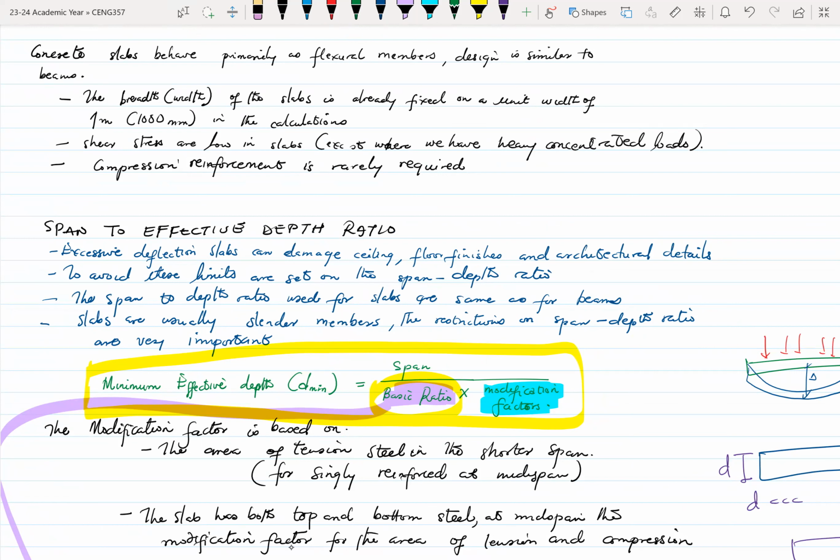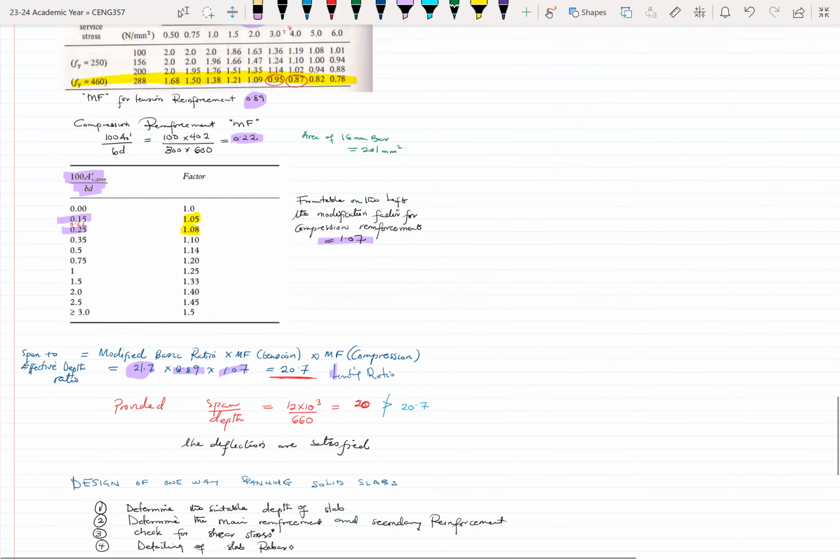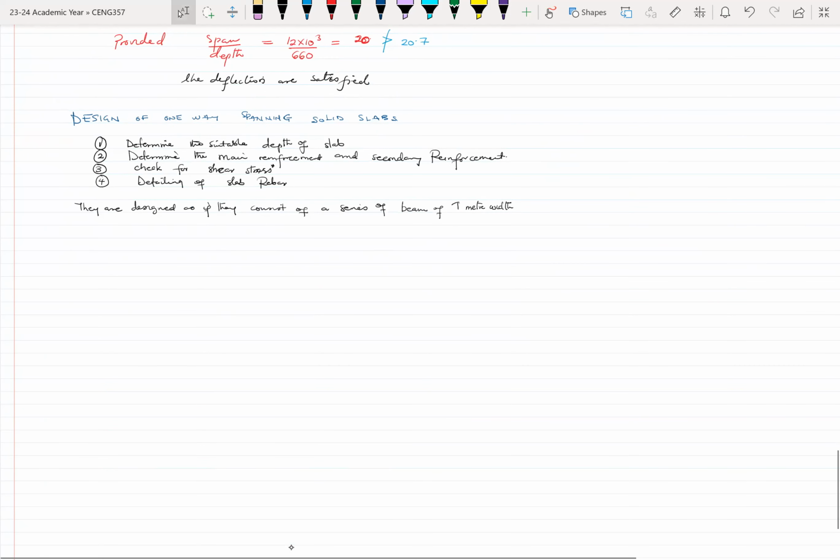They could be 2, 3 meters wide, but standardized designs require us to use per meter width of the slabs. So regardless of what slab you're looking at, typically you're looking at only a meter of it. Then whatever you get, you can extrapolate to the other length. So that's one thing. Design is up to 1 meter width.